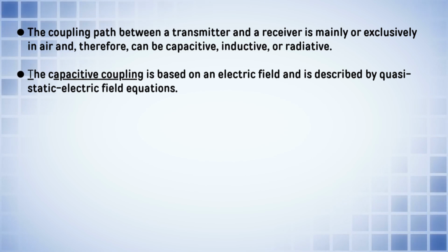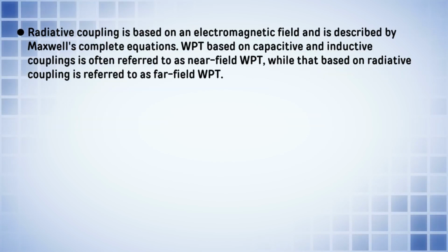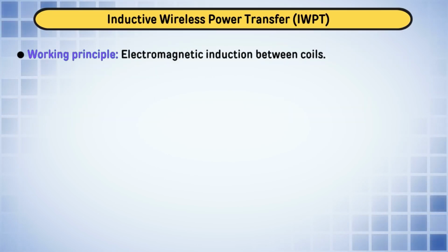Later on we will see that if the voltage gain is high, then we have to go for some other topologies, but these conventional converters can also be utilized to step down the voltage. So, 310 can be stepped down using a buck converter. You can see on the right side we have the topologies. Using one switch, one diode and one inductor, using these three components we can develop a buck converter.